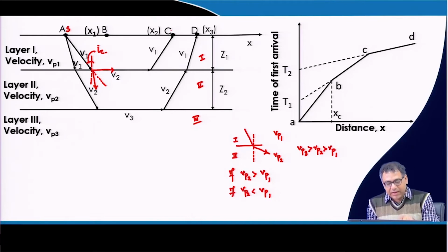This way the geophone will measure the first arrival time of the wave. Now if I take n number of geophone data and draw them with the x axis as distance and the y axis as time, then I will get this type of plot. Every change in slope indicates a change in soil layer. In the given plot there are 3 slopes, which indicates that there are 3 layers.